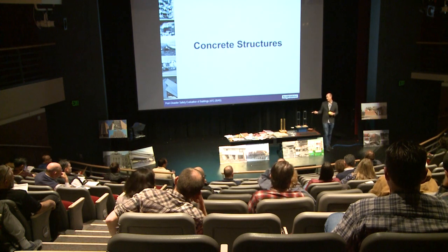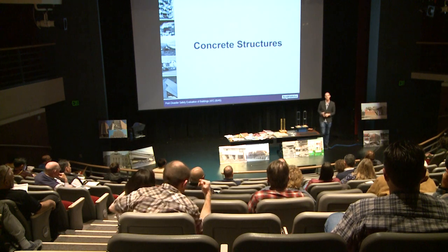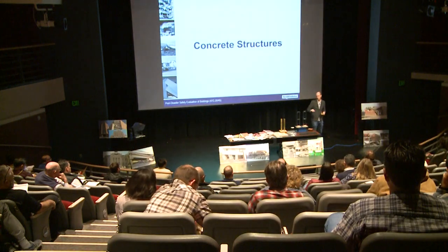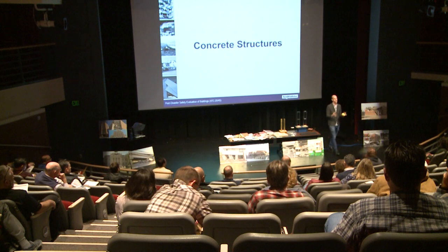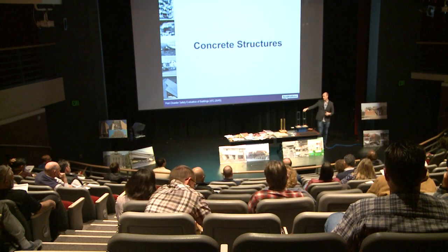And then, what about the non-structural systems? Do you think the more non-structural damage will be towards the top or towards the bottom? Because it's moving more at the top. So the movement is what largely causes damage, both from the displacement as well as the amplified acceleration.